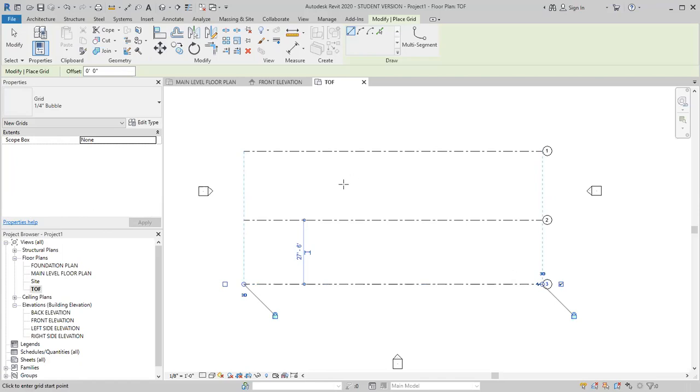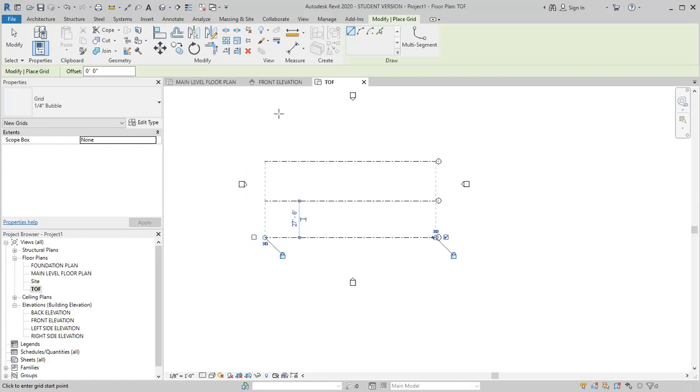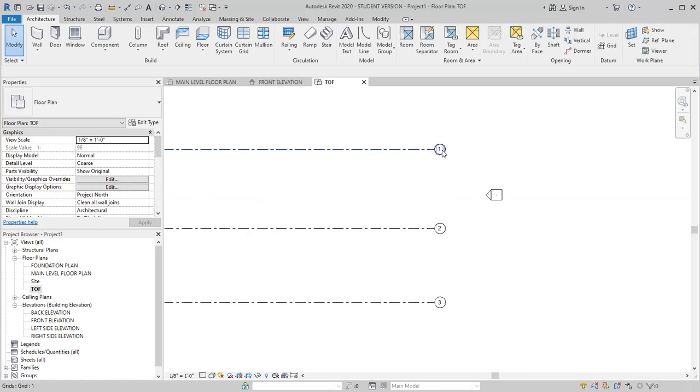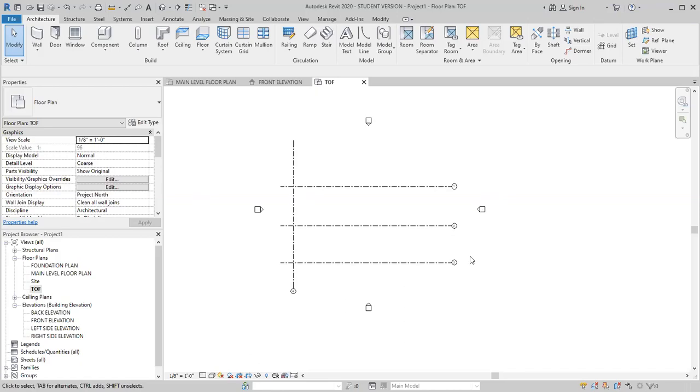Now let's add some vertical grid lines. So I'm going to come over here in the more or less the upper left-hand side. I'm going to click once, and I'm going to drag towards the bottom. Now, 2 things I want to point out here really quickly. I'm going to hit double escape to get out of that mode for a second. You'll notice that when I started with grid line 1, when I went to grid line 2, grid line 3, it automatically increased by 1 digit each time.